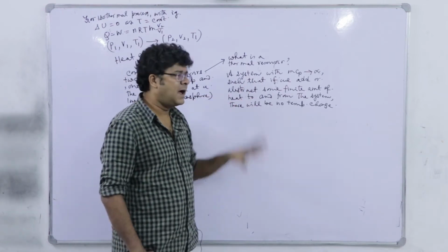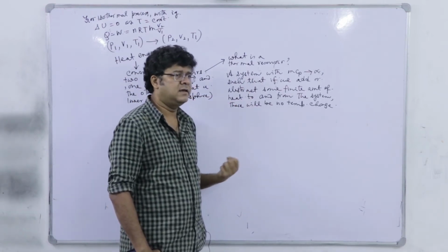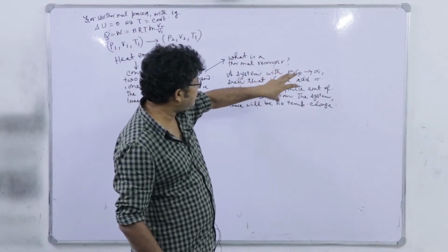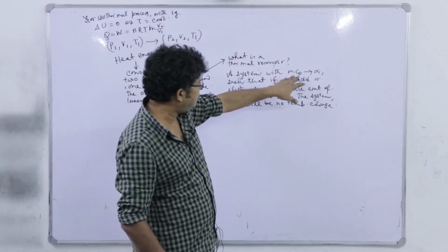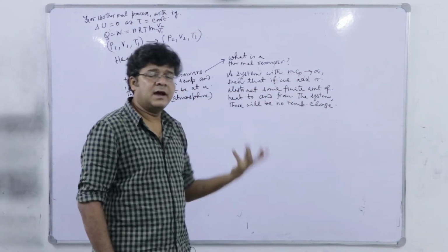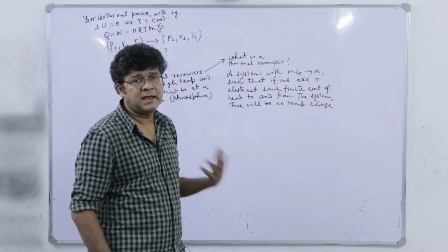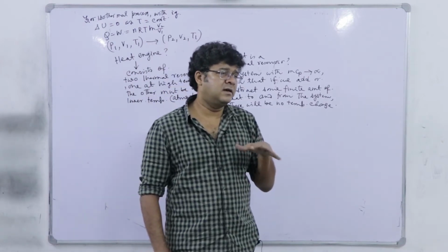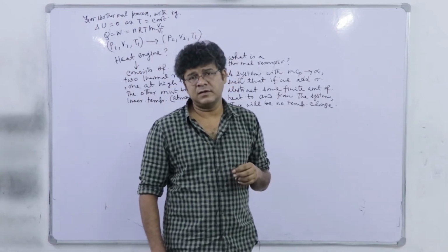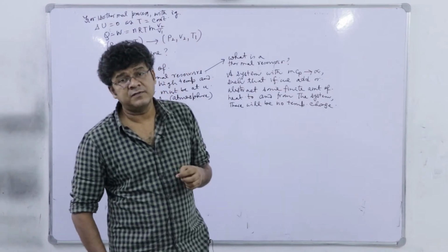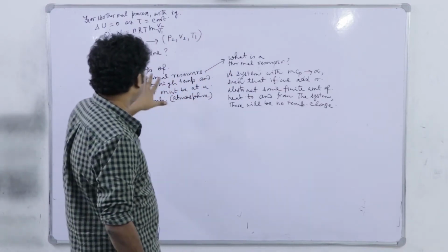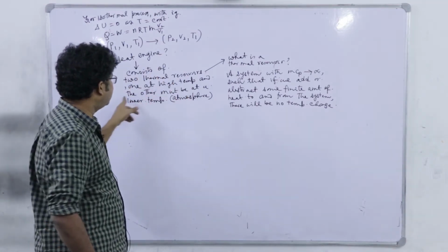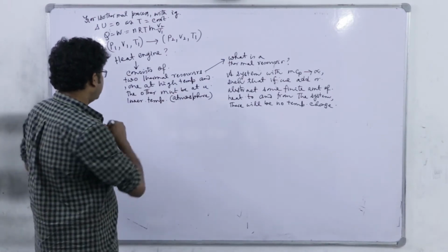So, even the high temperature object in real life, we cannot think of classically as matching the definition of heat reservoirs, but by adopting an alternative process of supplying this abstracted heat, we can think of it as equivalent to a classical heat reservoir, even with some finite MCP. So, anyway, it consists of two thermal reservoirs, one at high temperature and another at lower temperature.